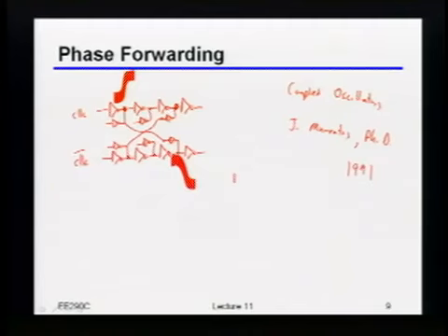So there's a dual constraint of guaranteeing that the thing still works. Because you can imagine if you make a chain that effectively has only 2 or 3 inverters in it, that would fail our original rise time versus frequency constraint, and it won't work at all. But you could back off a little bit from that and still make this mode the dominant mode, but just speed all of the inverters up by some fairly large fraction. So that's how you have to go about doing the sizing for these kinds of things.